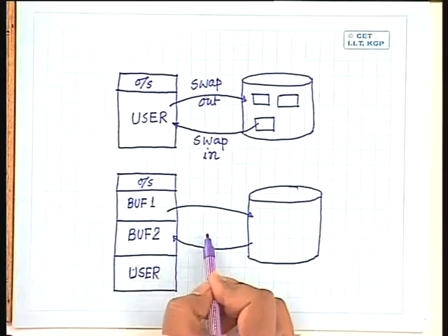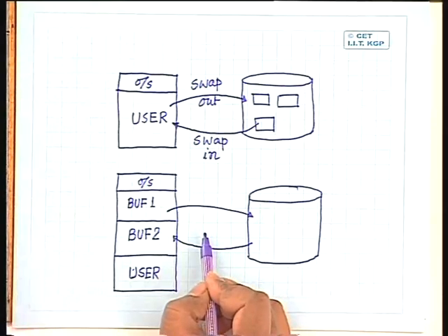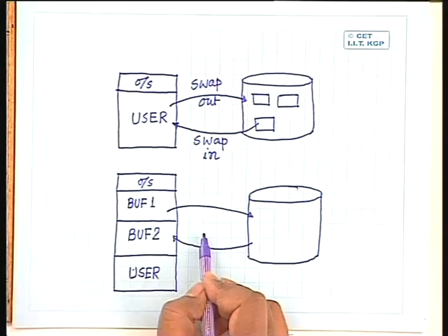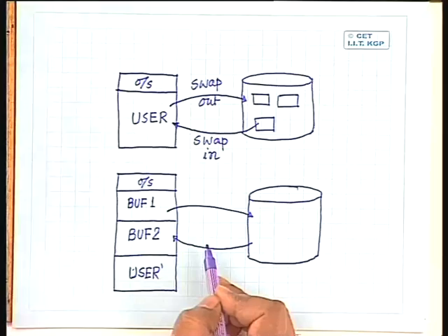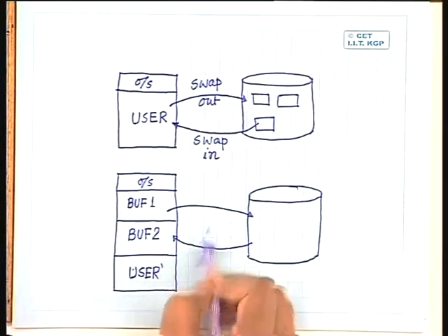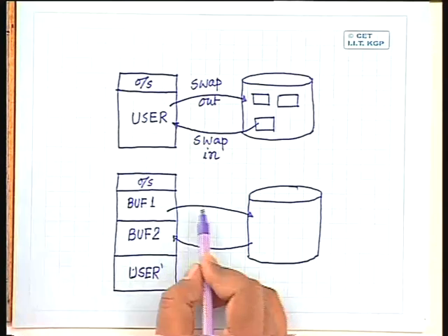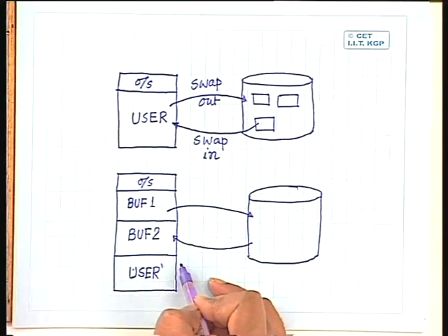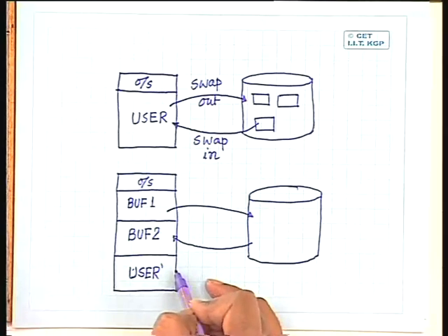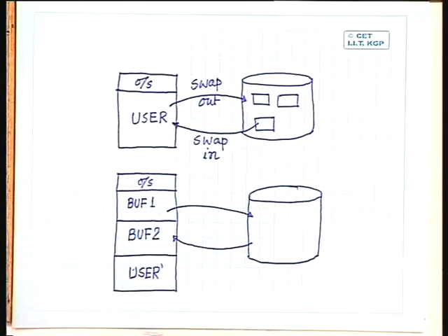Similarly, all of them cannot send data onto the data bus simultaneously, or get the data from the data bus simultaneously. Only one of them can send valid data onto the data bus. So even the access of the address bus or the data bus has to be multiplexed. That means the accessing of the entire memory has to be multiplexed.